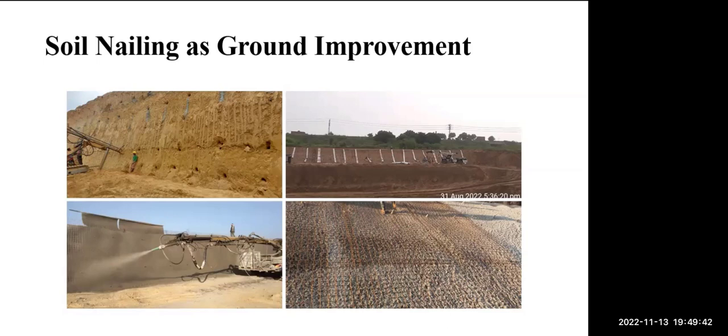It will not be just soil nailing design, or the length and spacing of the nails. We will discuss the different parameters affecting soil nailing, how to decide about long-term performance and short-term performance, as well as the durability of these nails, and the different nailing approaches, especially for deep excavation. For example, we will show some dedicated freight corridor projects, DFCC projects, with deep cut excavation using soil nailing as a ground improvement.